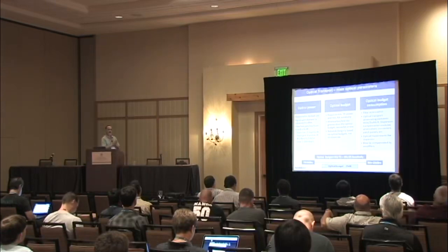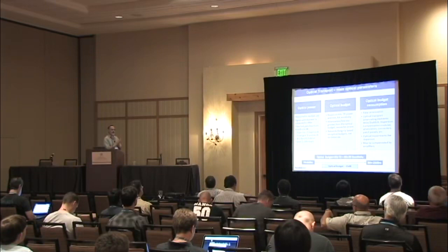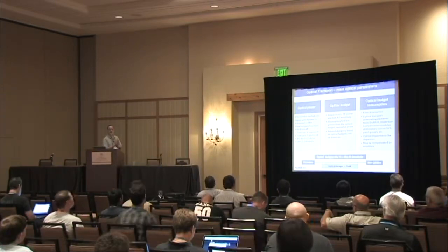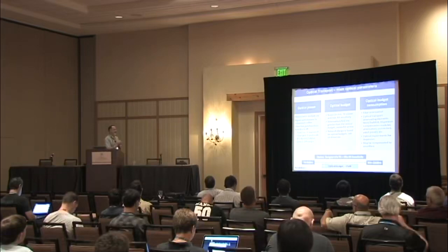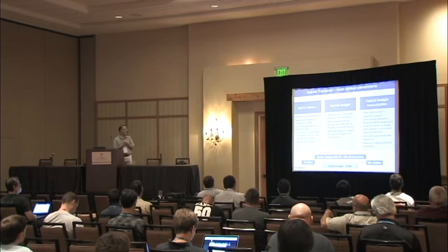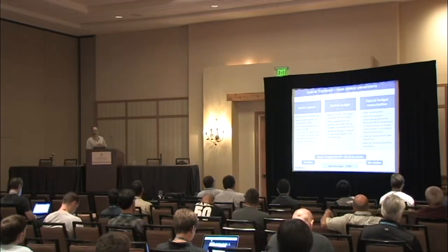If your link generates attenuation beyond this optical budget, you are prone to have errors. And in general, network design is not based on distance. It's based on measuring your optical budget and the requirements of your fiber. Now, who are the consumers of this optical budget?